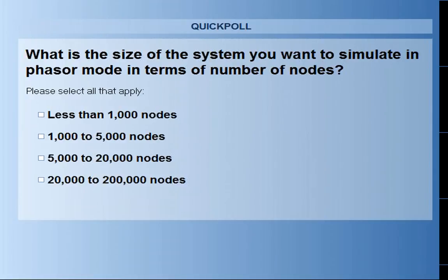So just to give you an idea of how this model is integrated with ePHASORSIM, I will show you what it looks like behind the scenes. Here is the general model that we have for RT-LAB. This block, which is called solver, is the main block. This is the heart of ePHASORSIM. If you click there, you can link it with an Excel file.